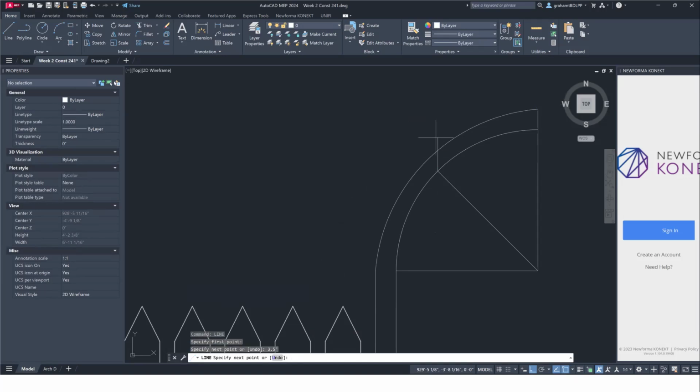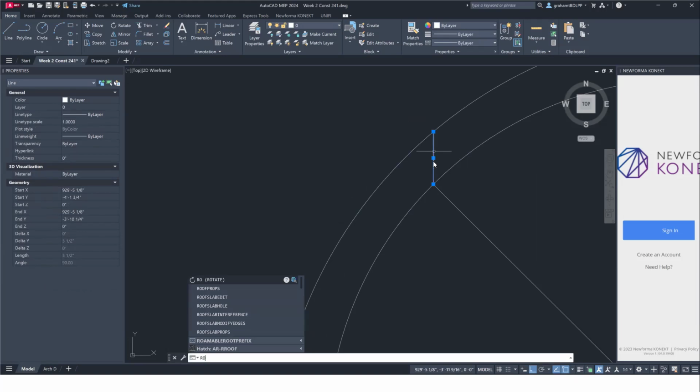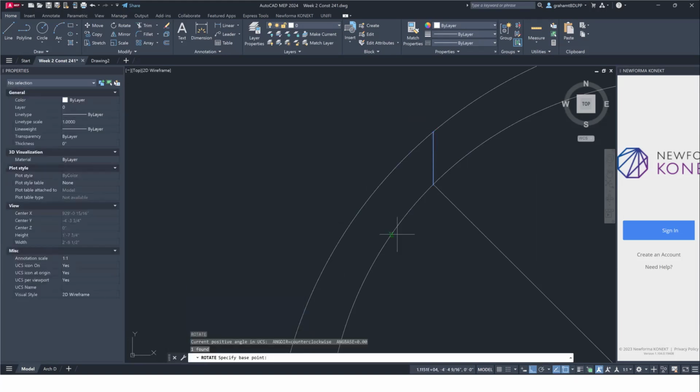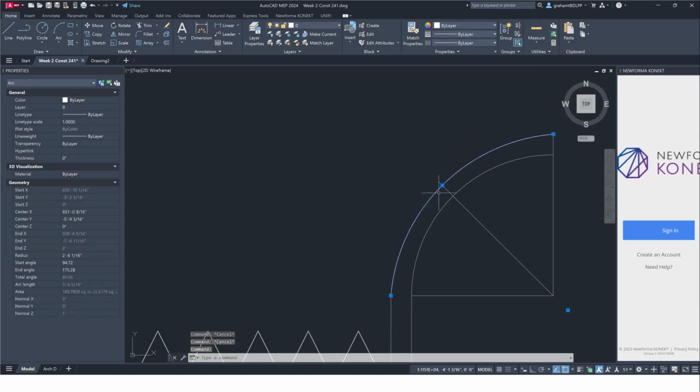3.5 inches. And then I'm going to rotate that with the base point being right here, and I'll rotate it 45. Since my ortho's on, it doesn't want to snap, so I'll turn that back off. Make it 45. And now my outside arc, I can move this midpoint.